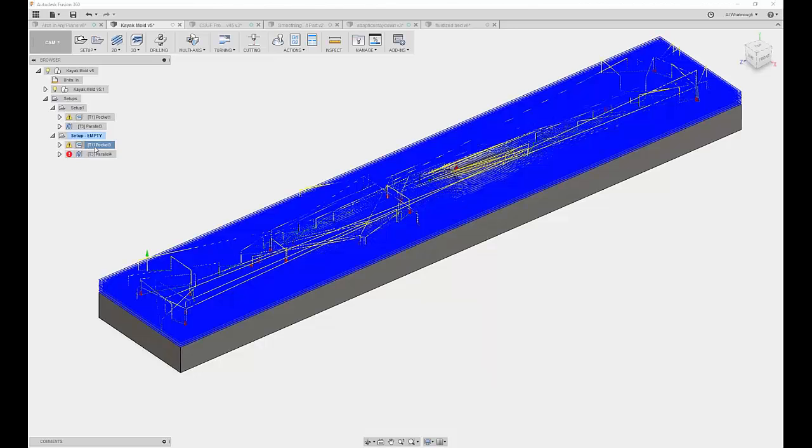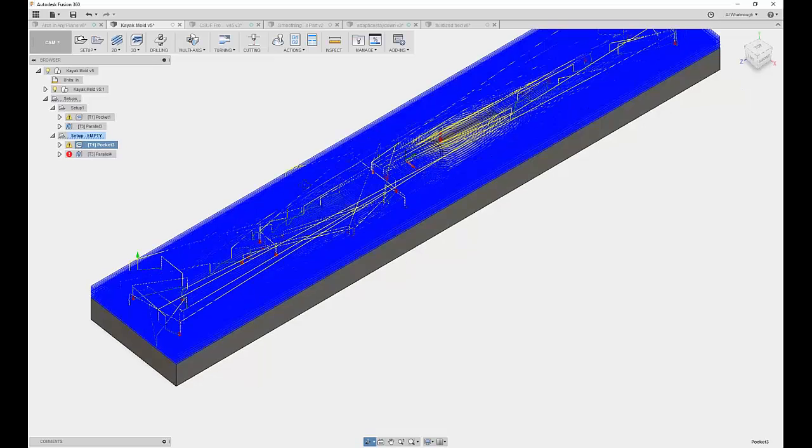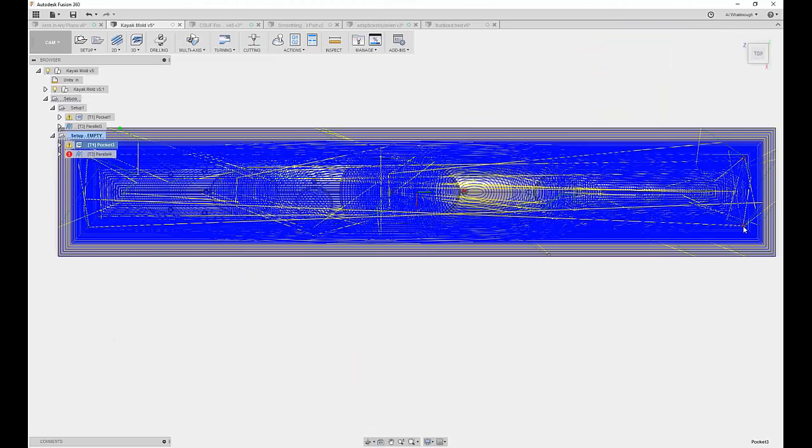There's some long ones here that would probably catch you. So see these really long rapid movements that's going from this top corner to down in the bottom corner. You'd think that it's going to go the way the crow flies. Many machines accelerate all the axes until it gets to the right number. So if you're going over 30 inches in X and 2 inches in Y, X and Y are going to go at the same speed until Y has hit its value, and then it just goes across in X until it gets to its value. So you end up with a 45 and a straight line. So it's not going in the direction you asked it to go in. It's going to do that dogleg.